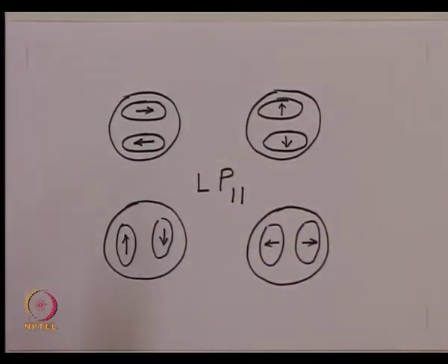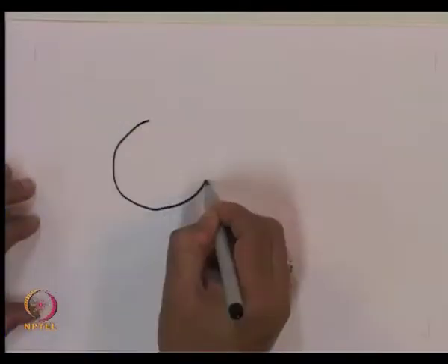So, in fact, whenever we launch a light with arbitrary polarization inside a weakly guiding fiber, and if the excitation mode is LP11, in fact, we have a combination of these four modes which will be propagating simultaneously inside the optical fiber. Same thing then one can ask for what is the situation for LP01 mode, and LP01 mode as we saw is circularly symmetric.